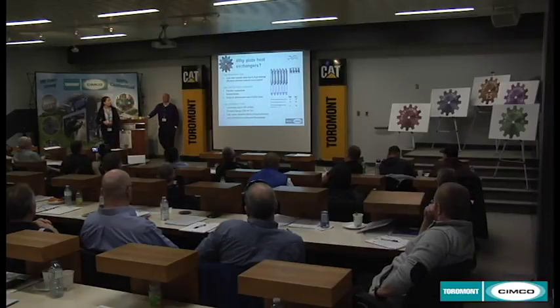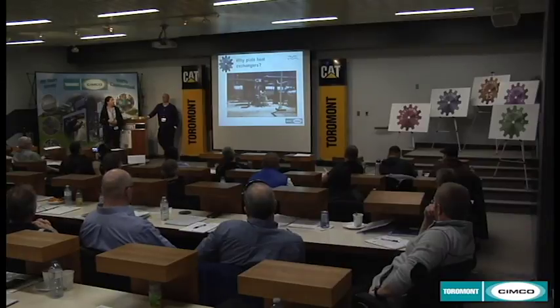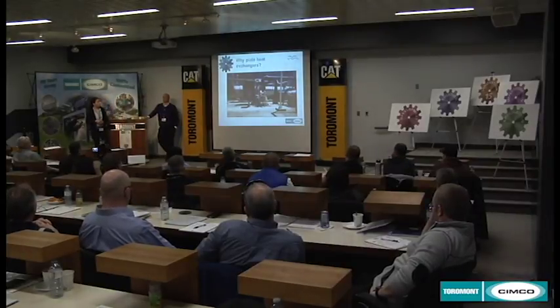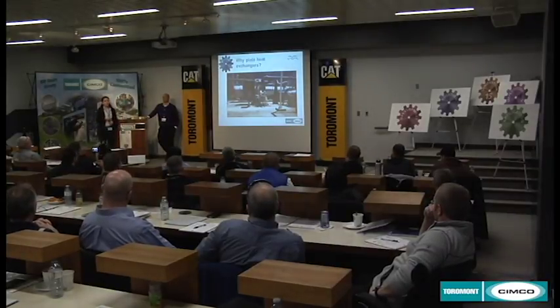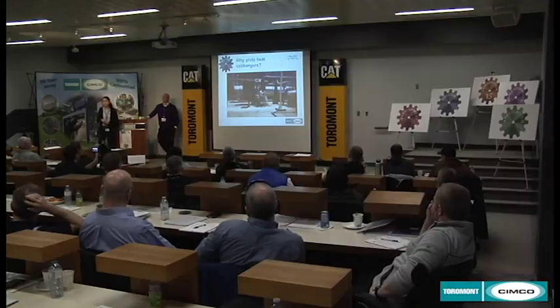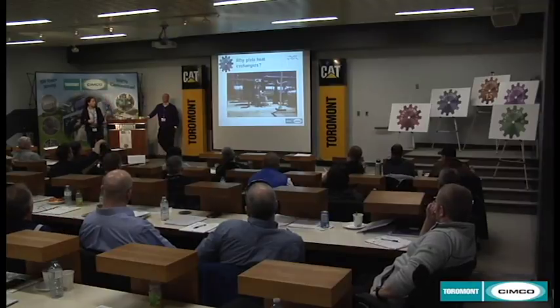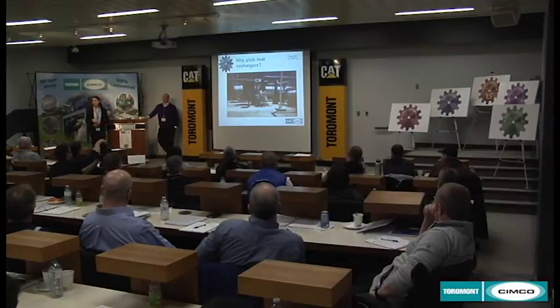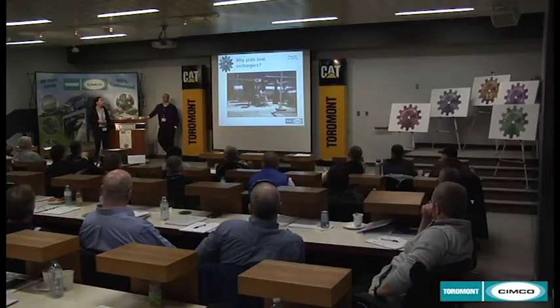It's quite a big difference. And here we have a slide with a picture showing the same duty with two different heat exchangers, a shell and tube and a plate heat exchanger. And as you can see, it's a very big difference in space requirement for plate and frame than shell and tubes.